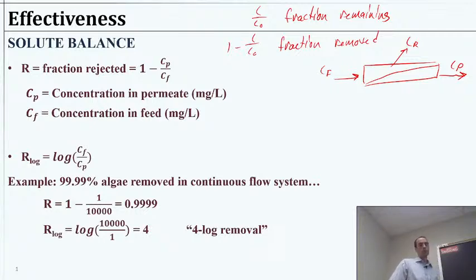Now, we should be able to do a mass balance. A note here, just to make it very clear: for a membrane system, we generally don't see it accumulating meaningful amounts of our solute. Yes, we will have fouling, but if we were to do a mass balance, we're not going to notice that substantially in terms of, are we accumulating stuff? It's just not on a time scale that will really affect the flows, the amount leaving rejected or permeating, on a mass balance type of thing. So we'll assume, in that sense, a steady state.